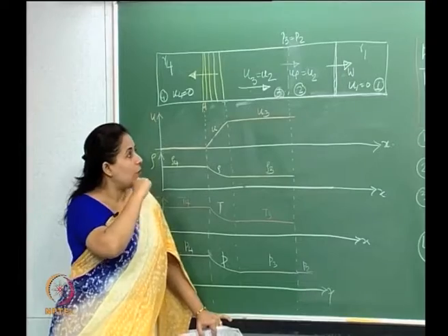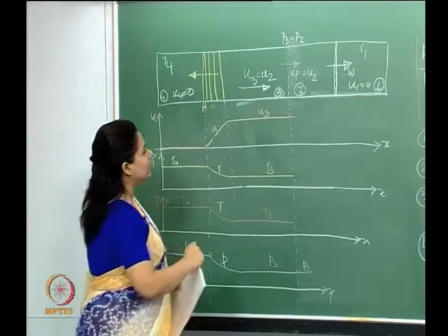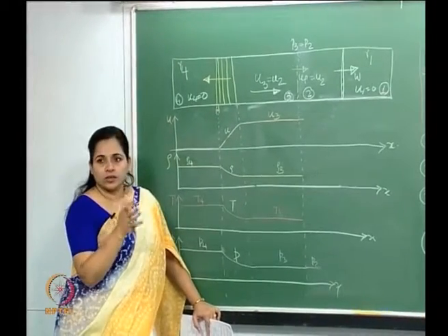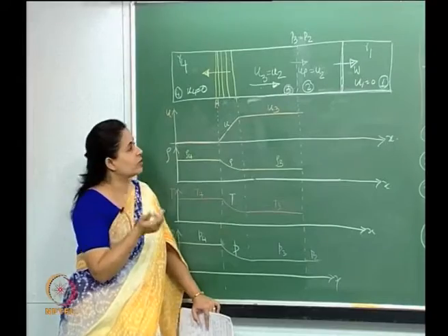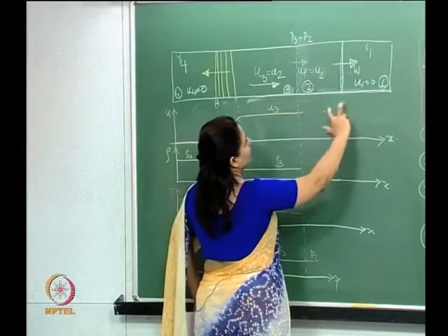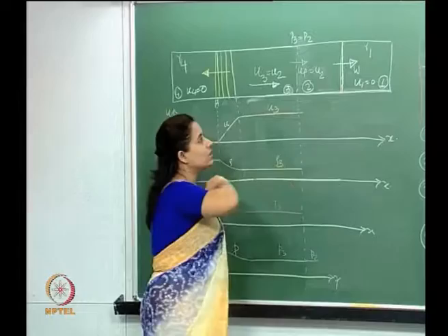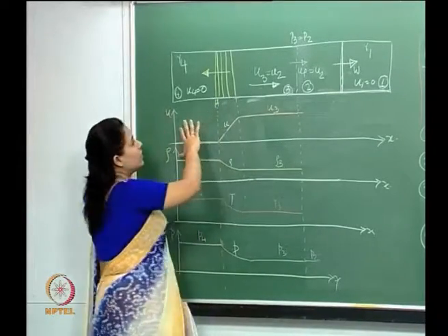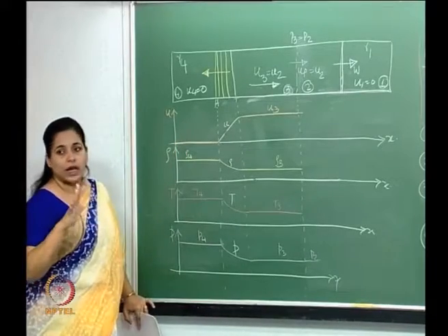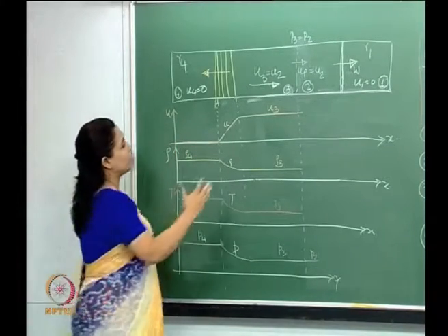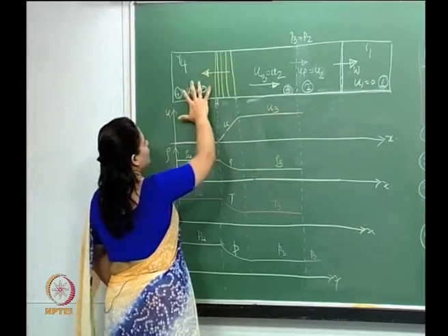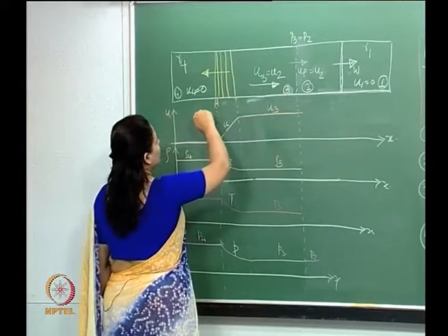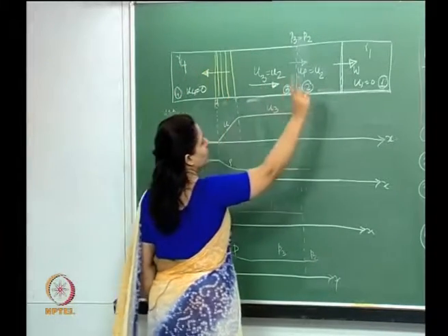And what we've seen here, of course, is that unlike the steady case, where the incoming Mach number governs the nature of properties behind and after the shock, here it is governed by the pressure ratios across the shock wave. So for a given diaphragm pressure, initially when we have the diaphragm, we have just region 4 and 1, with pressures P4 and P1.